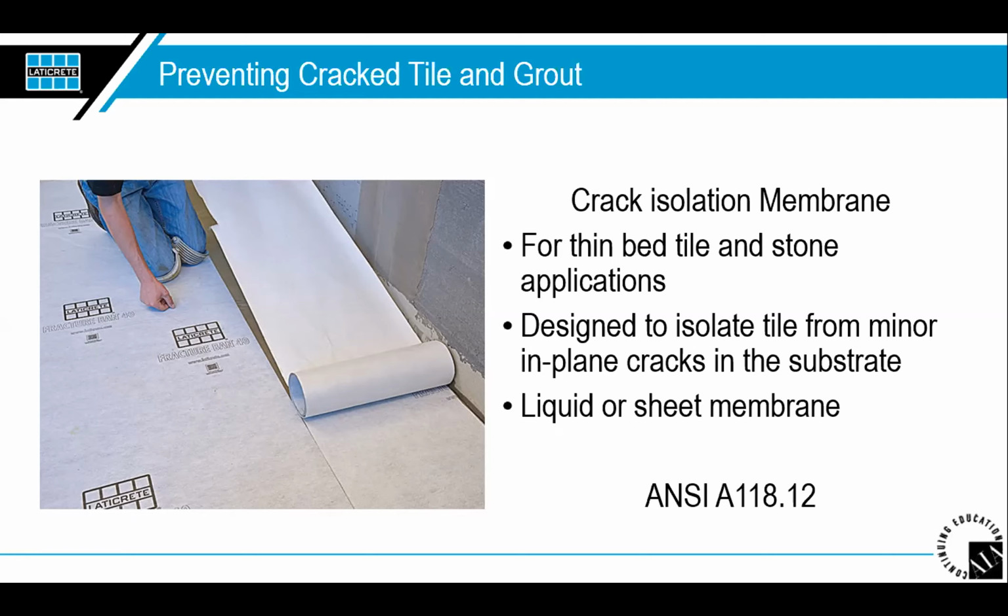Again, in most cases, what we're just trying to do is protect the finish of the tile and stone. Like we said, it's very expensive. We don't want to see it ruined by cracks that are coming up that we know are going to occur in the concrete. So we should just be using the anti-fracture membranes in general. But it's not always a requirement, depending on what the ownership is looking for.